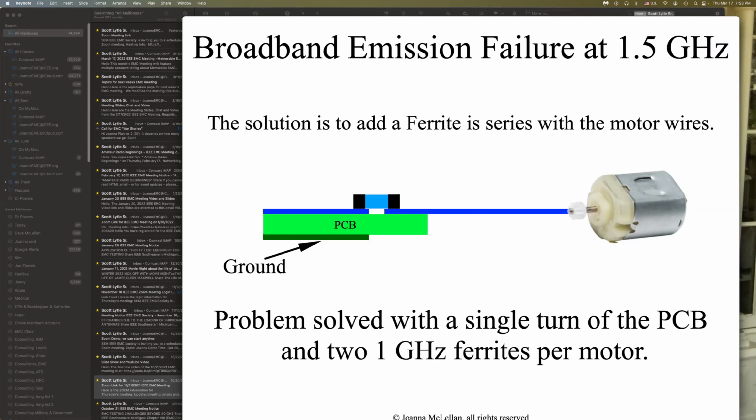Yeah, a lot of people don't realize that you have to have two different size capacitors in order to deal with different frequency ranges, even when you're trying to shunt an IC. Because what we call a capacitor is actually a combination of capacitance, inductance, and equivalent series resistance. What its impedance is depends on your frequency of operation. At some point, it becomes resonant.